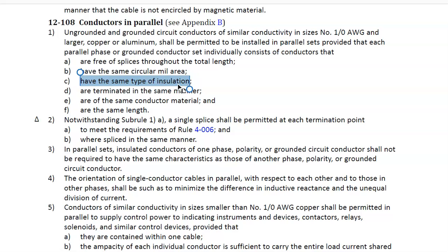Temperature during installation, we talked about that last time. Once again, cold weather installation: do not install anything below minus 10 degrees unless it is rated as being so. You're going to find those rules in your Appendix B.